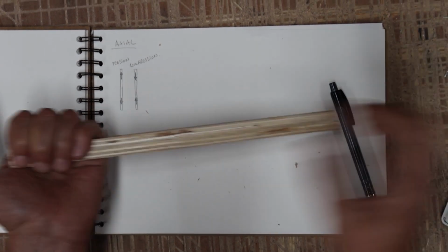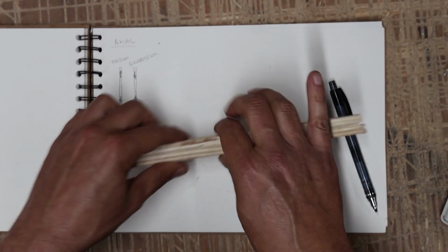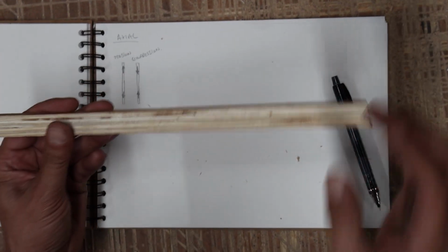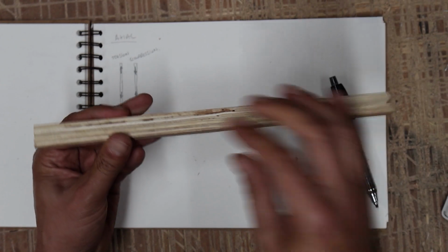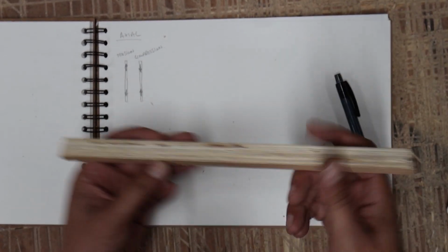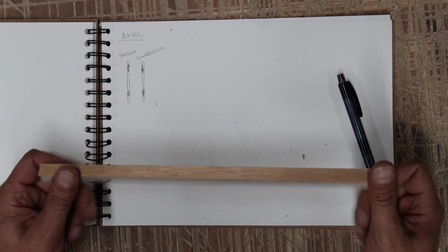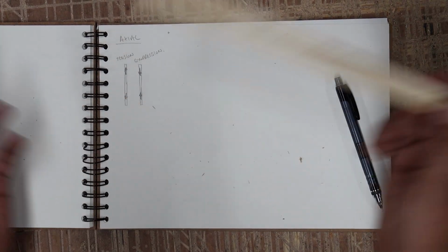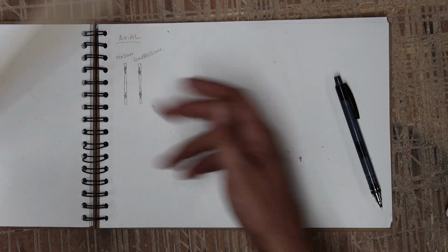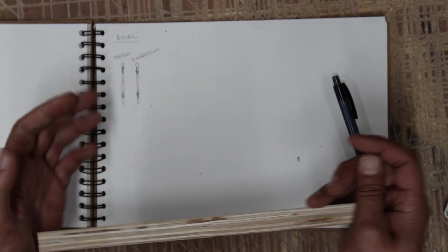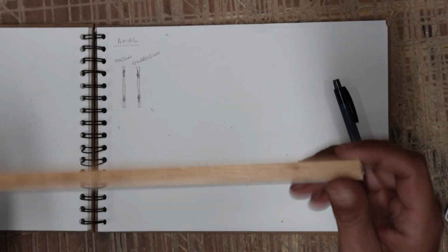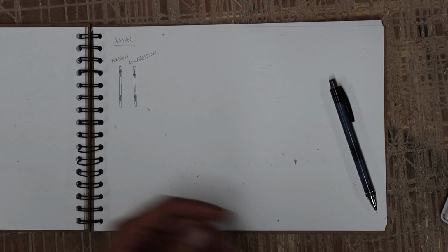The only mode of failure is for this thing to yield, to pull apart from itself. It's such a fundamental mode of failure that it demonstrates the real fundamental nature of the material, and that is why we use it to define different materials. Now, for compression, we have a different mode of failure, and that is buckling. I'm not going to be able to exert enough force on this member to show you buckling, so let me go grab a different piece of wood.